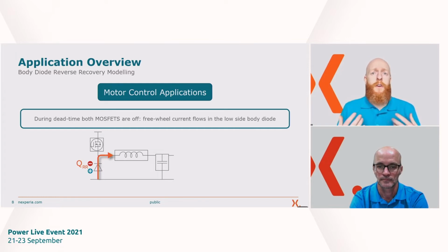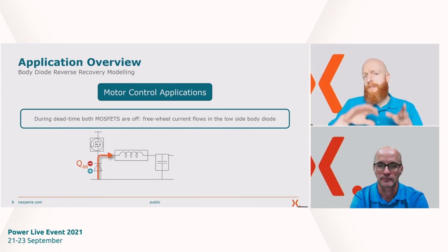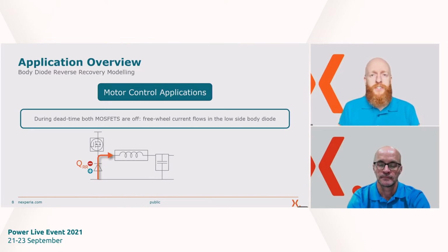And the crux of the matter is that the sooner you can detect EMI issues, the cheaper and easier it is to mitigate them. You don't want to wait until you've got a physical prototype, that you've done all your designs, you've passed all your testing for normal operation, and then you send it off to an EMC test house to find out then that you're not conforming to one of the standards, at which point it's very difficult to make changes to your design and it's going to be costly.